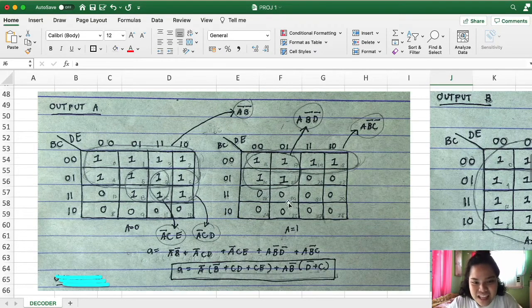Sorry, my bad. And then for the right matrix, up here on the top, since our first group was able to encompass all 4 columns, we effectively cancel out D and E. Then since it only occupies a single row, both the literals on that row will be included in our minterm. And since the unchanged bit for those 2 literals are 0, it will be 0, 0. So B and C are both inverted. So for this one, we will have A, not B, and then not C.